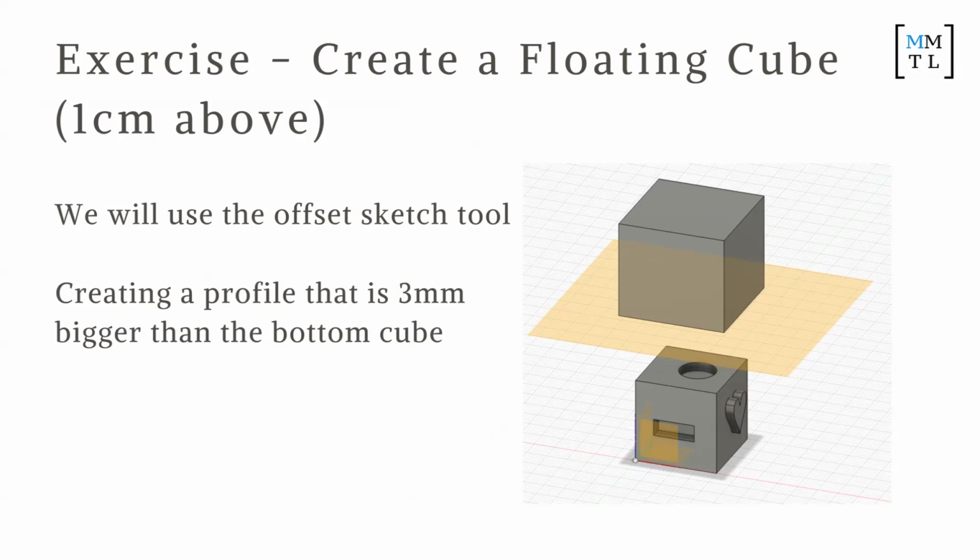And a little tip: just make a new cube. With the construction plane you made, you can actually drag out the edges to make it bigger. So you can choose how you want to view your construction plane, you can make it bigger or smaller, which is useful later on.